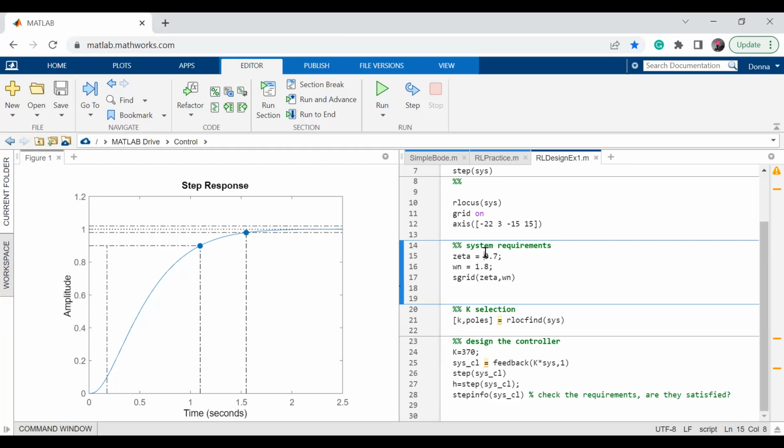So do you remember if we plot the root locus, some parts of the root locus are unstable for some K, and we need to change the shape of our root locus. So we know a pole is like a magnet. Wherever you put it, the rest of the root locus will go toward that. It will change the behavior of the system.